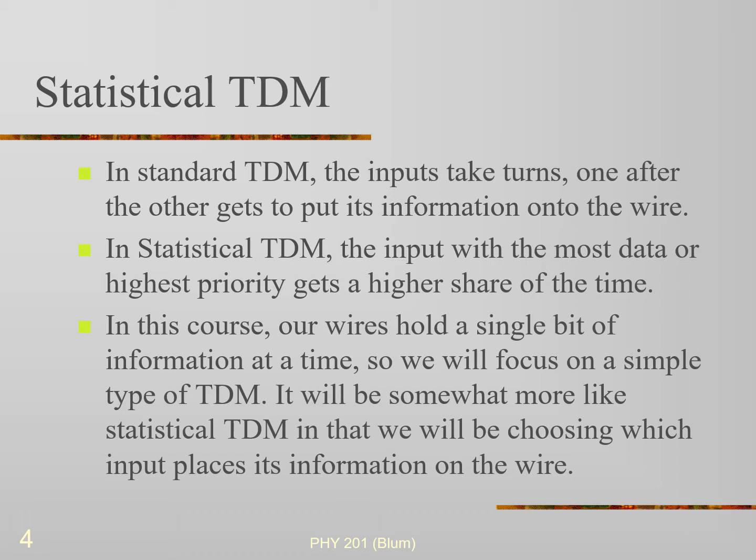It's important that you understand that we are not combining signals in any way. We're not putting them through an AND gate or an OR gate. We will have some mechanism to pick one of the sources, say source number 3, and then that bit, whatever it was, high or low, is what gets through the channel. So we're not combining it in any way with other channels. It is selected and then it gets through. The others are blocked. End of story.